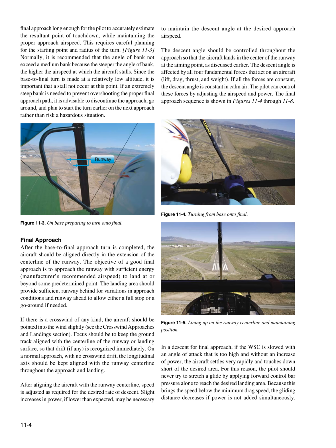The descent angle is affected by all four fundamental forces that act on an aircraft: lift, drag, thrust, and weight. If all the forces are constant, the descent angle is constant in calm air. The pilot can control these forces by adjusting the airspeed and power. The final approach sequence is shown in figures 11-4 through 11-8.